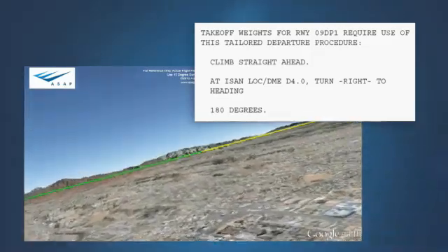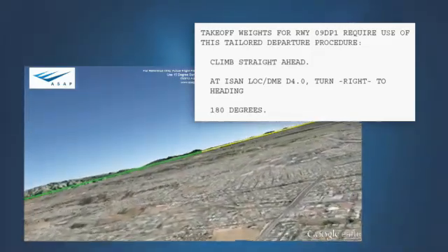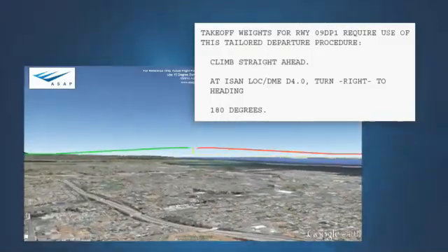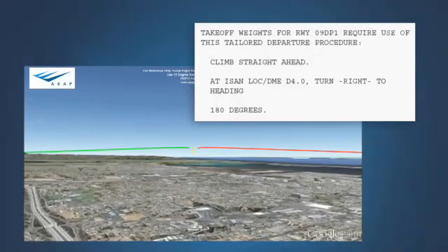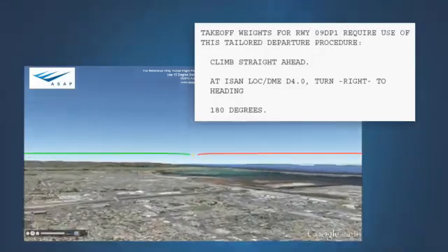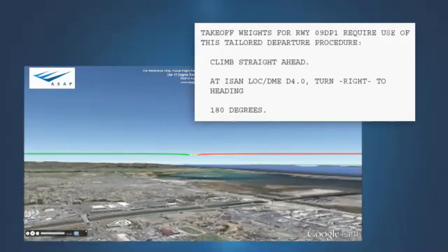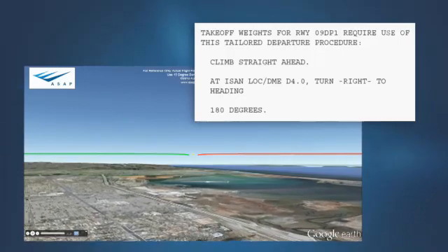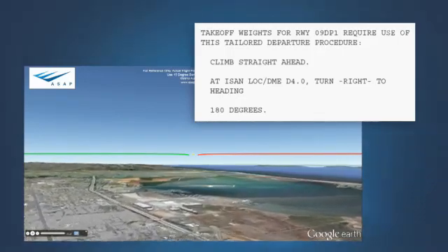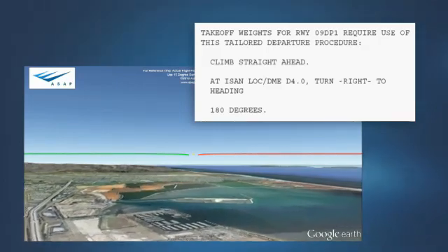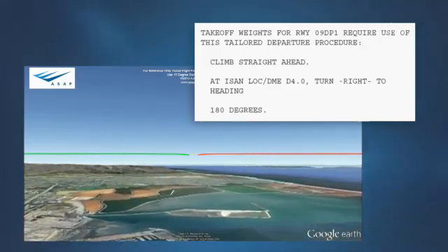The effect on climb performance resulting from the bank angle flown during the turns is included in the allowable takeoff weight limit. Because a turn is involved, the obstacle accountability area expands in width to 3,000 feet either side of the track. The procedure may be defined in simple terms of turns and headings to fly following an engine failure. Ground-based navaids are usually used to identify the point at which a turn is to begin. Oftentimes, it is beneficial for the engine failure procedure to coincide with the IFR departure procedure used for that runway.